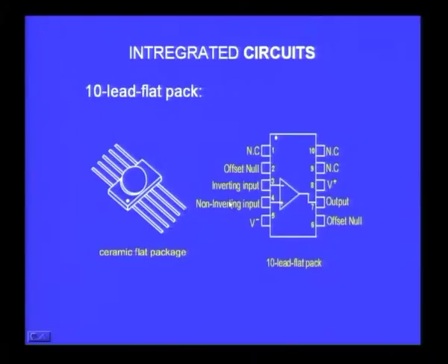You also have a 10 lead flat pack, where you have a flat pack with 4 plus 4, 8 pins on either side, and that also is another package. This is not generally for general purpose use, we use either the metal can or the plastic.